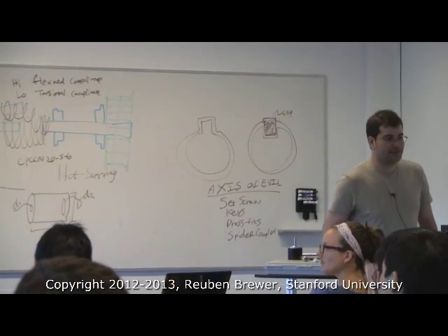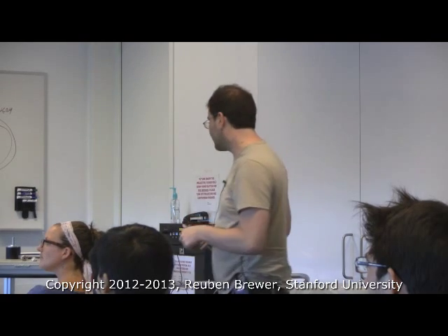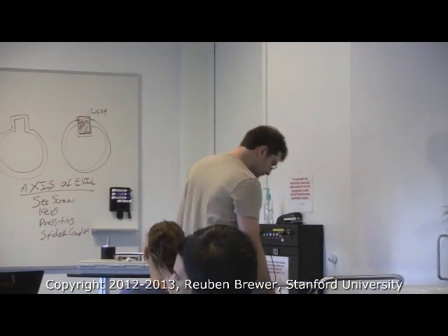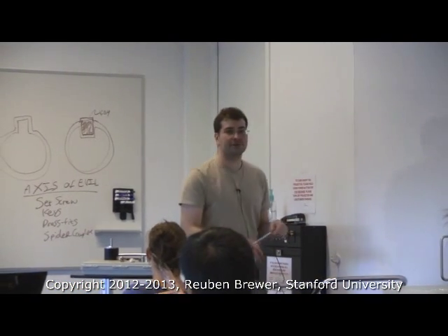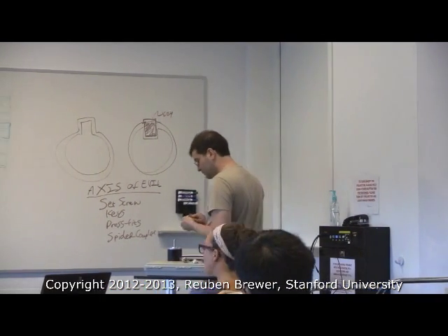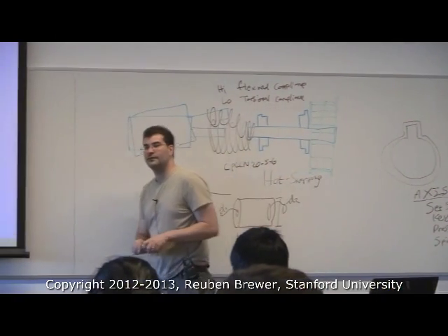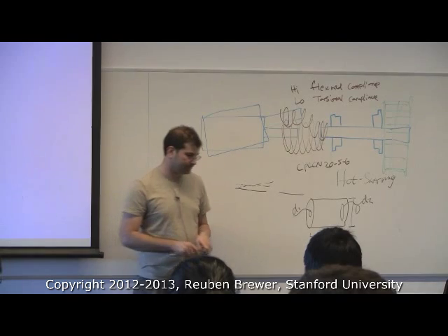That's bad. This is a DC motor, right? Not a stepper? Is everyone sure you're holding a DC motor, not a stepper? It's a DC motor, so DC motors are for continuous rotation, not incremental. So why do you have little detents in it? Cogging.